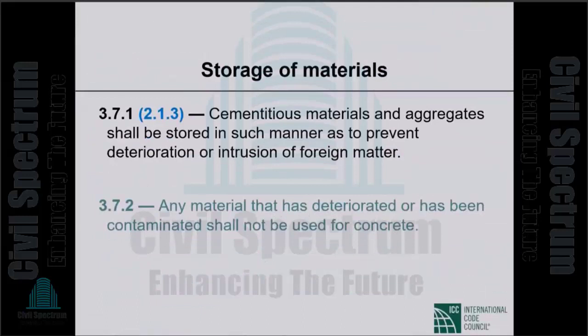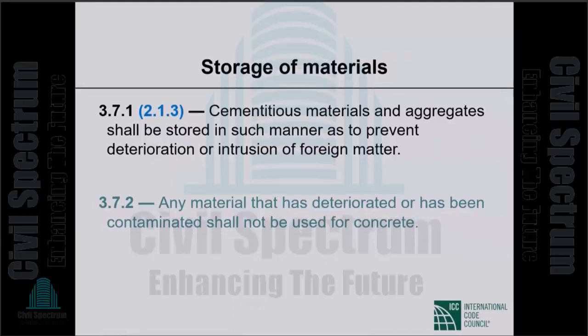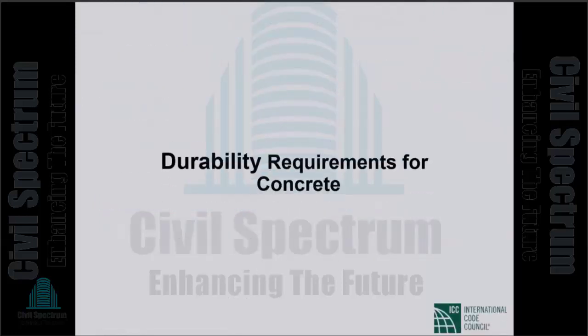Storage of materials: cementitious materials and aggregates shall be stored in such manner as to prevent deterioration or intrusion of foreign matter. Storage is extremely important. Prevent deterioration and intrusion of foreign matter. These things, when you read, don't read like much, but these are very, very important requirements.